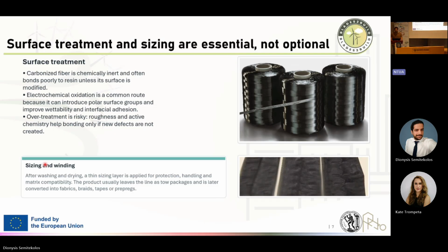And we have developed a methodology in the lab. We have designed and produced a pilot line where we can treat fibers in a continuous format, and we can put carbon nanotubes, that you saw Vangelis, for example, yesterday, synthesizing through solvolysis waste. We can use those carbon nanotubes inside the sizing solution that we have, and then apply this sizing solution on the fiber surface.